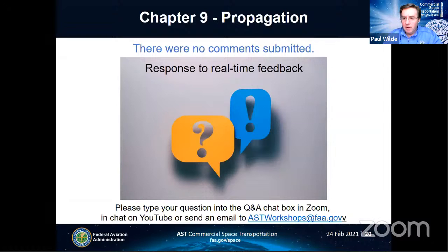I did. Thanks, Eric. That's a really great question. The winds can indeed have a significant influence on the debris, and it can be quite complicated. But the point I wanted to make is that with statistical winds and their perturbations, the most difficult aspect is getting the inter-altitude correlations correct. So you typically need a covariance matrix based on past data to understand how those inter-altitude correlations can be modeled reasonably.